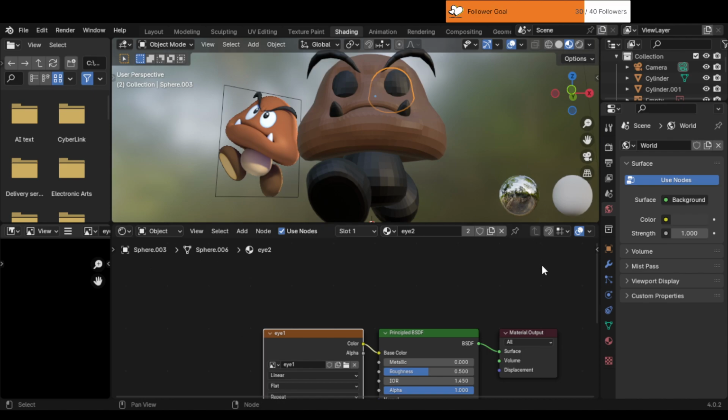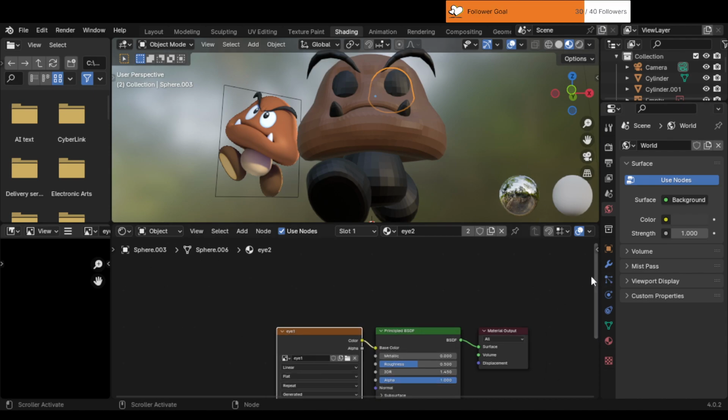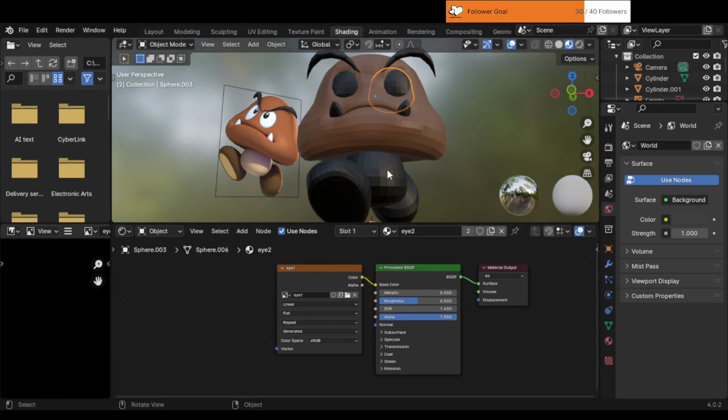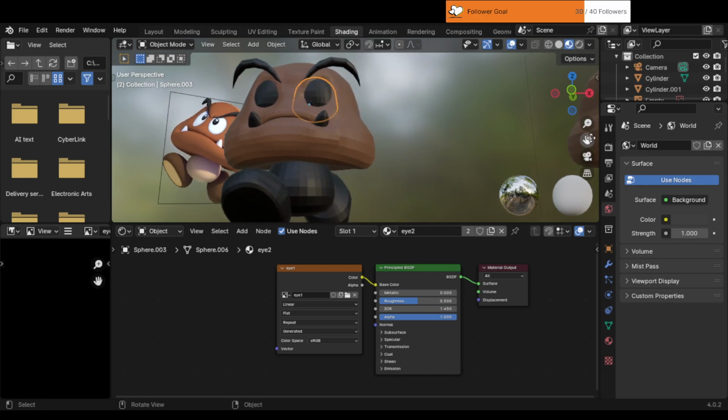3. Check the scale and normals. Scale. Ensure the scale of all meshes is set to 1.0 for X, Y, and Z axes. Normals. Make sure all normals are facing outward. Alt-N, recalculate normals. 4. Try applying transformations. Apply all transforms. Select the joined items and apply transformations.